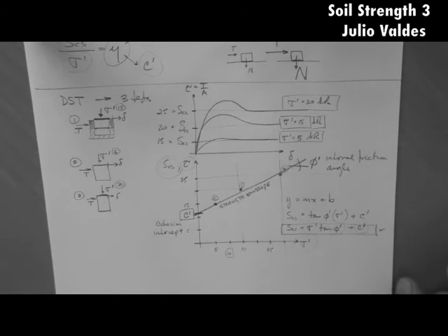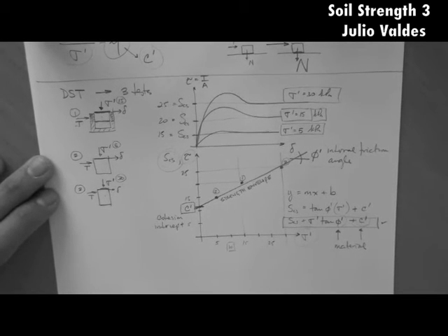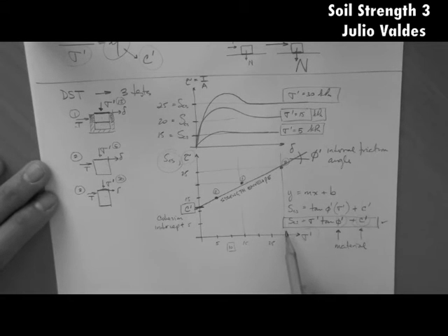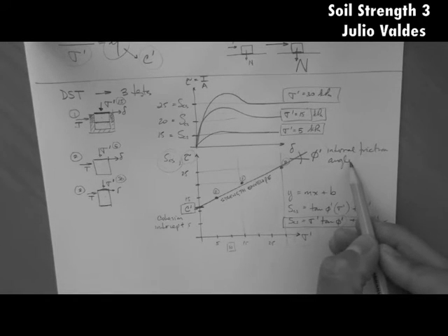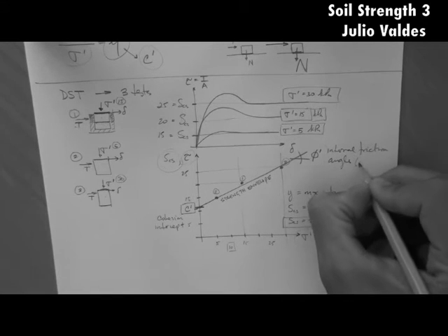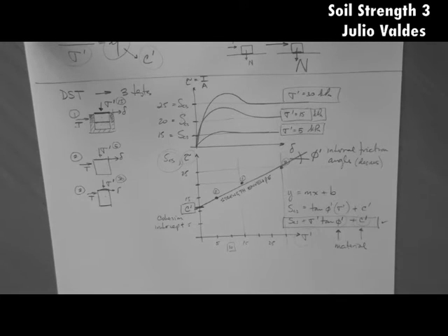When we run direct shear tests, or we want to determine the strength properties of a soil, strength parameters, we're looking for that one and that one. These are material dependent. Okay, they vary from soil to soil. Some soils have C prime equals 0. I'll tell you a little bit about this in a second. Okay, now, well, let's discuss these two before we actually do an example where you will see how this is used. The internal friction angle is an angle, of course. The units are in degrees. Okay? And that tells you the relationship, again, the slope, right, which is a relationship between this and this. The effective stress and the strength.